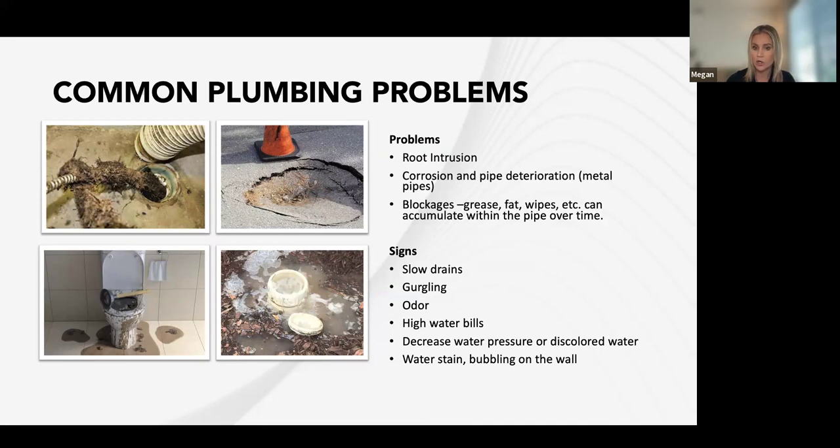So slow drainage, gurgling, if you hear that sound, definitely get it looked at. Odor, or smelling anything, especially a sewer smell, that means you definitely need to take a look. High water bills, decrease in the water pressure, discolored water, any stain or bubbling on the wall, or hot spots on the ground. Those are all signs of water possibly leaking. So definitely take a look.